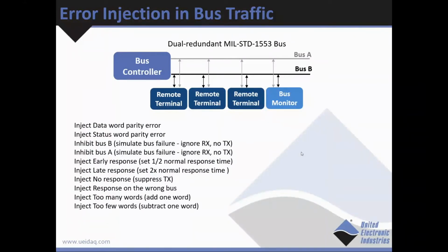You need to inject errors to prove out your design so that you can be confident that your design will handle real-world issues once it's deployed. In simulators and maintenance trainers, error injection is used to simulate a fault on the 1553 bus and help the person at the controls learn to deal with the issue. Better to do it there than up in the air.